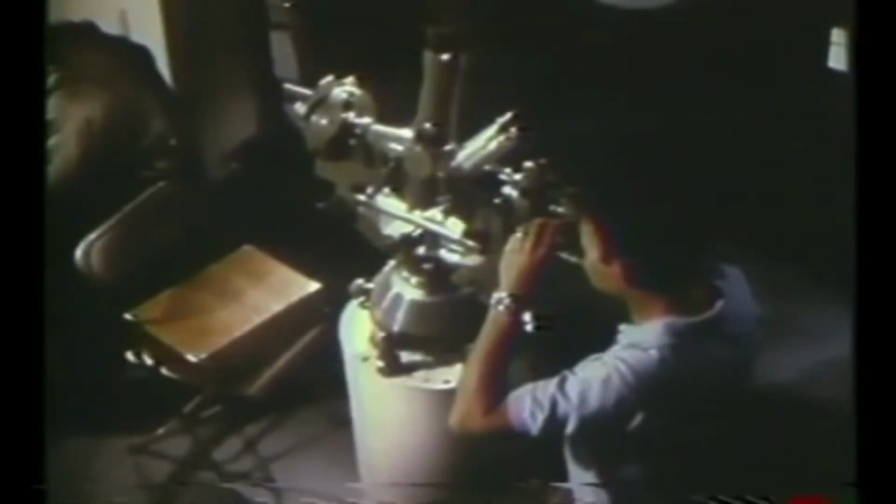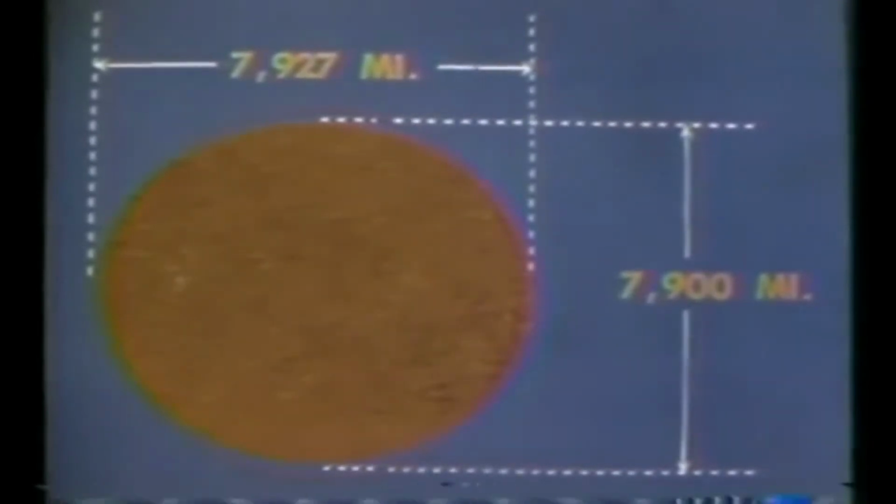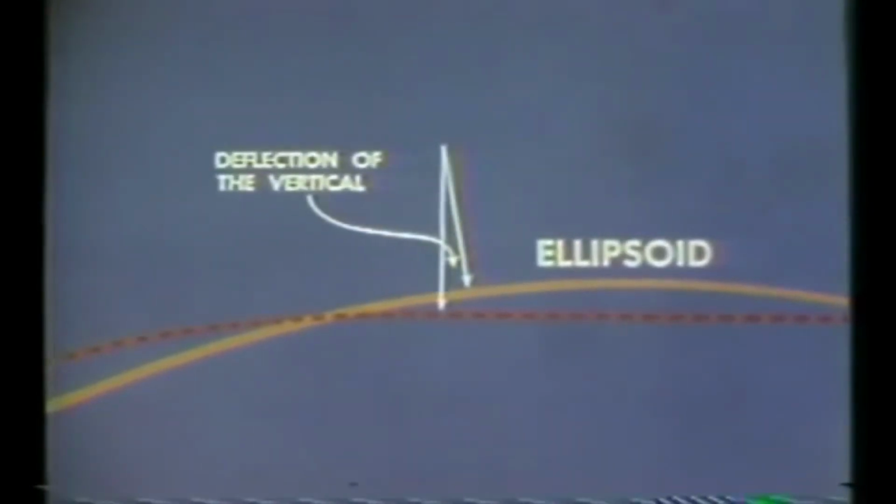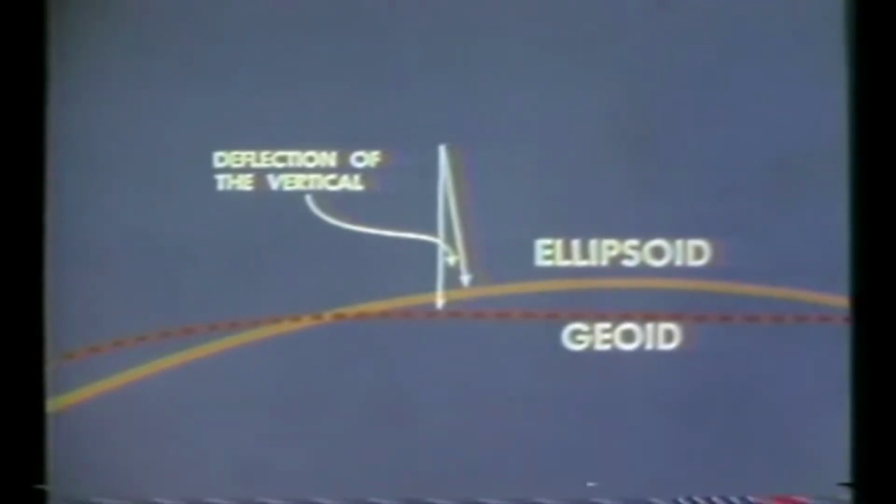Conventional first-order geodetic control procedures involve measurement of the altitudes of celestial objects with respect to the terrestrial horizon, which is defined by the direction of gravity. The Earth's figure is, rather than a true sphere, an oblate spheroid or ellipsoid, produced by the centrifugal force of its axial rotation. For purposes of accurate surveying, a geometric figure formed by the average surface of the seas is adopted. This irregular surface, everywhere perpendicular to the direction of gravity, is called the geoid.